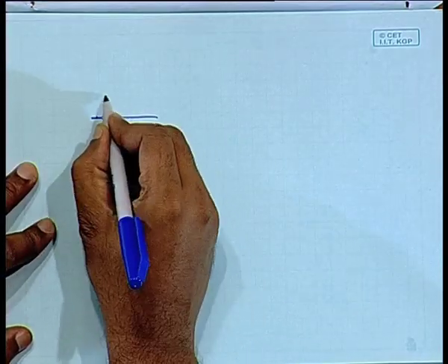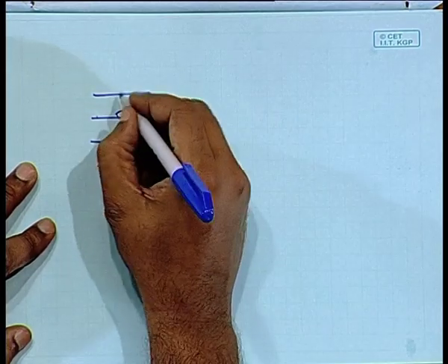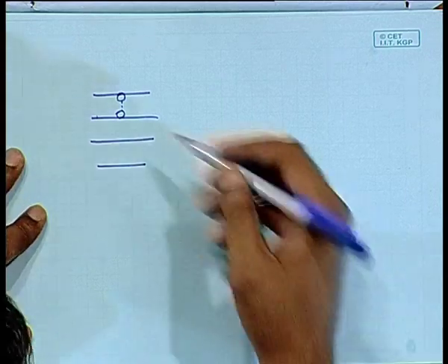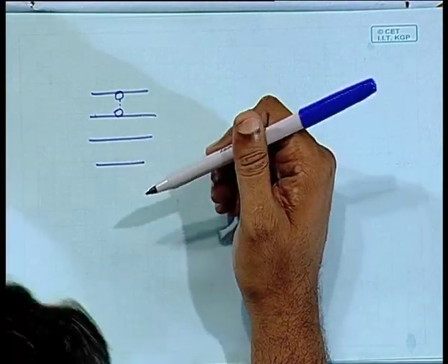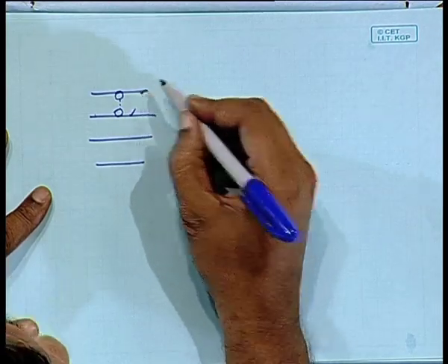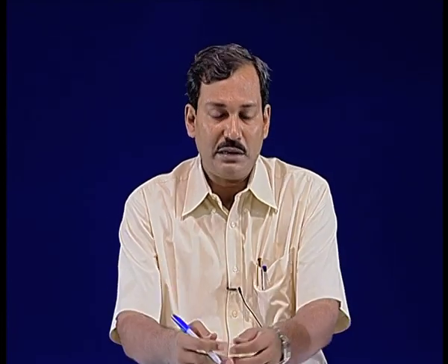If you have one cylinder like this and another cylinder, then you have one surface resistance, a second surface resistance, and a resistance in between. So three resistances in series. The only complication is that A1 will be different from A2. That's the only difference. Nothing beyond that. Conceptually, it's going to be the same again. That's more or less about the network method in radiation.